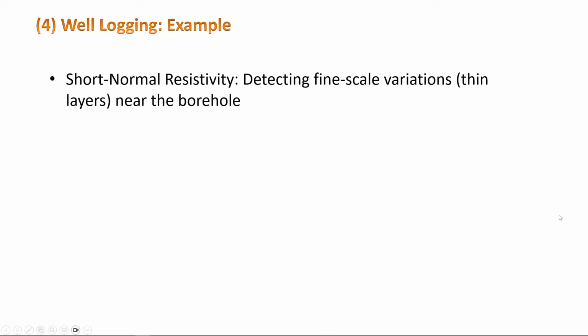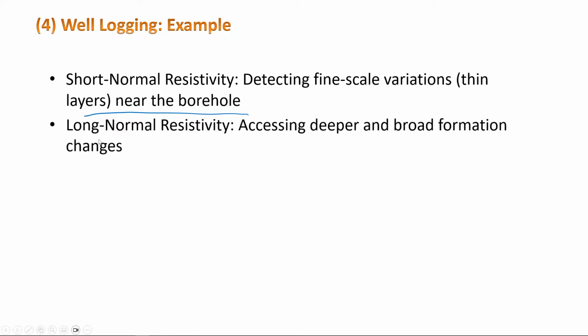So let me show you this example. Borehole geophysics, like short normal resistivity, detects fine-scale variation, like thin layers near the borehole, for example. Long normal resistivity can access deeper, broader formation changes. So this can go deeper, just as I showed you.